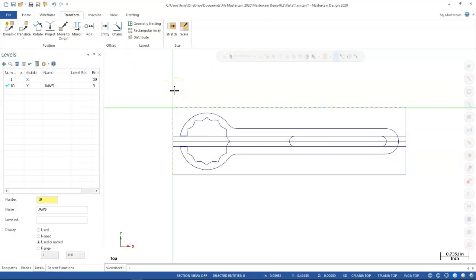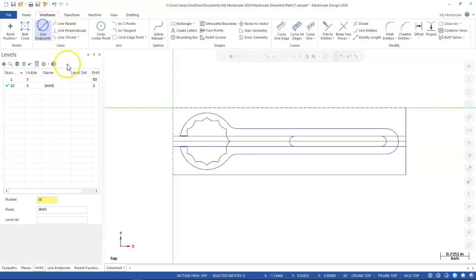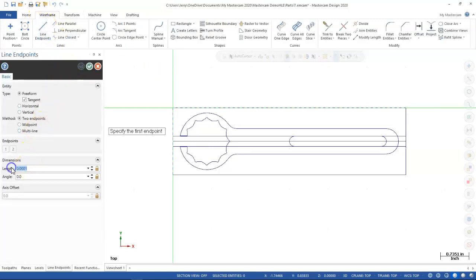So don't really have a preference. I just know that my soft jaw is going to be 6 inches wide. We were 1.625, so if I was making these, it would probably be around an inch. Doesn't have to be perfect. We're either going to go pull something from stock that, we took a bar and we blanked out all of our soft jaws, and we're just going to pick those items. So 1 inch should be plenty for the depth,